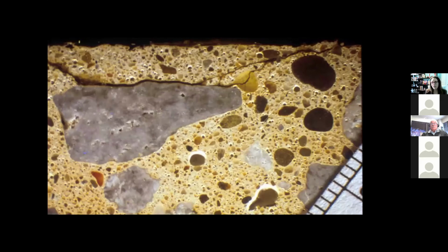The reasons for mortar flaking, there's a variety of them. It could be due to bleeding the surface, being a very popular reason for it. Not as common anymore, but say you had a high bleed on the surface, someone might be sprinkling cement on the surface to soak up that bleed water and then finishing it in.